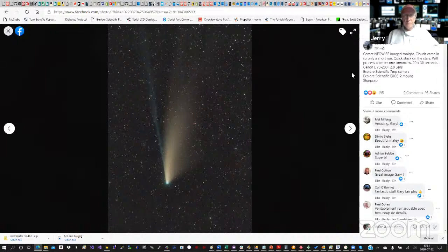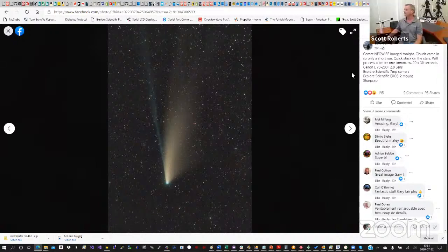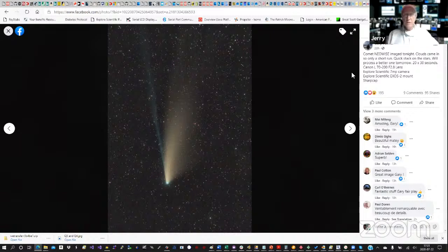I had him do that, and then I got on Zoom and reset the connection. I sent a command to show the version of the firmware. I sent the ESV command manually in the advanced tab on the configuration manager, and it came back. So I said, oh, good, the controller's working. It's running. It can receive commands. Then I stopped that, switched it back to wireless, and he brought up his tablet, and it worked.